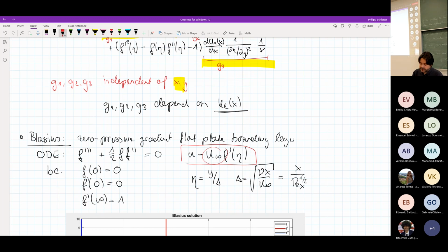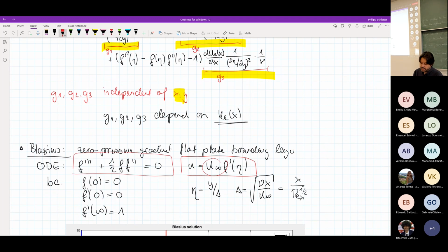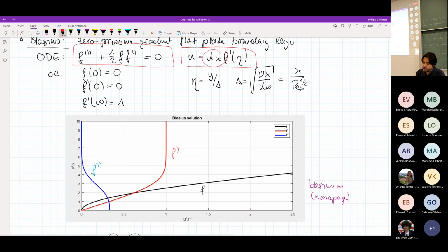And in that case, we could then see that this general equation reduces to a quite simple ordinary differential equation, non-linear though, which means it's a bit difficult to solve, but it's in principle a very easy equation. The solution to this equation would then give us f prime and f double prime. And with the knowledge of this f, we can then calculate our profile in terms of u, v, vorticity, and so on. And I guess that's where we got last time.